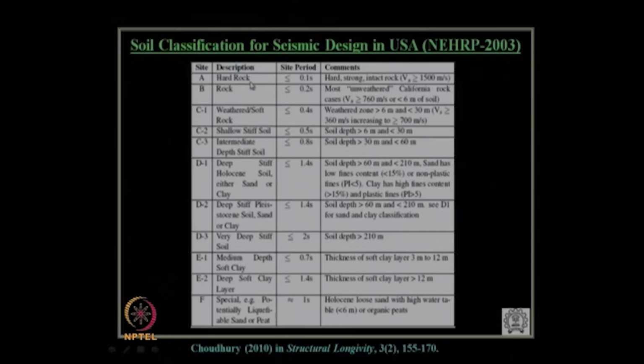As you can see over here, how these have been classified with respect to the site period. What we have discussed in our ground response analysis, we get a site period which is more important for our design rather than any other static values. Also, we should know what the shear wave velocity is, because shear wave velocity is one of the major important criteria which shows the dynamic nature or characterization of the soil.